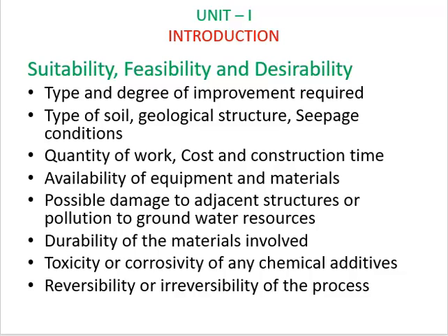The next point is availability of equipment and materials. Some ground improvement techniques require sophisticated equipment and also skilled labor, and some materials are not available everywhere. Hence, these things should be assessed before selecting the ground improvement technique.